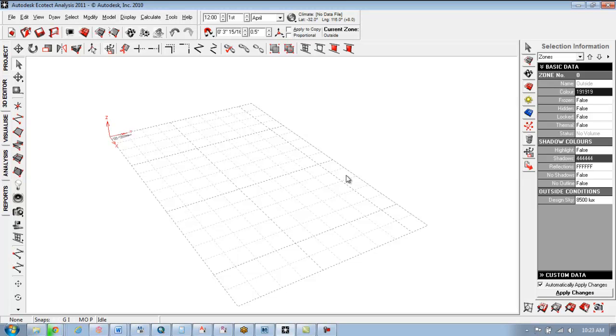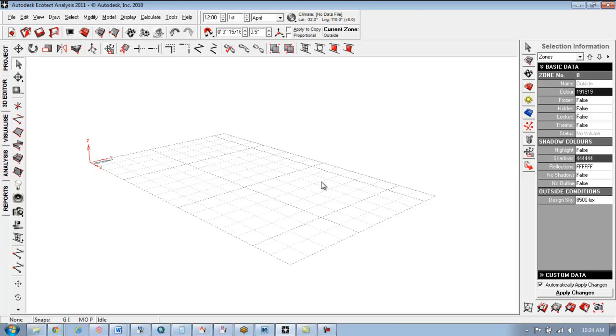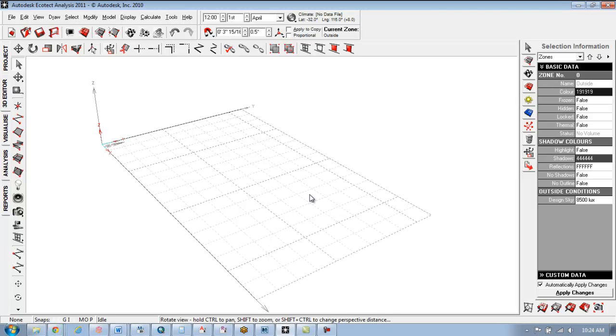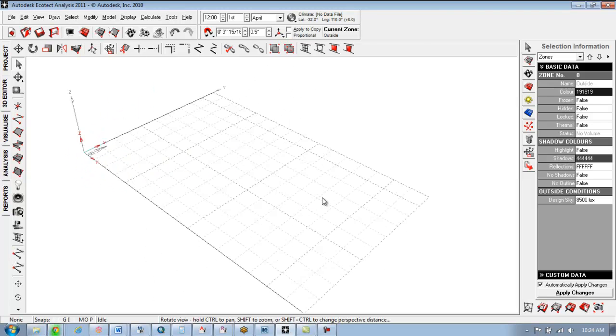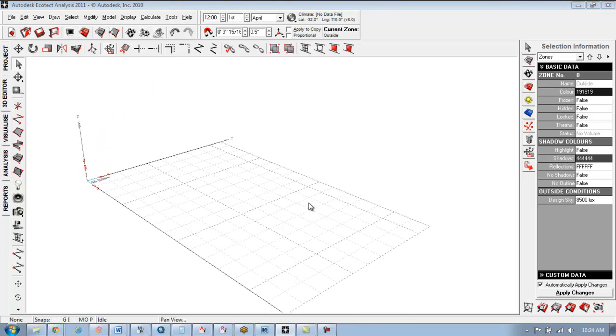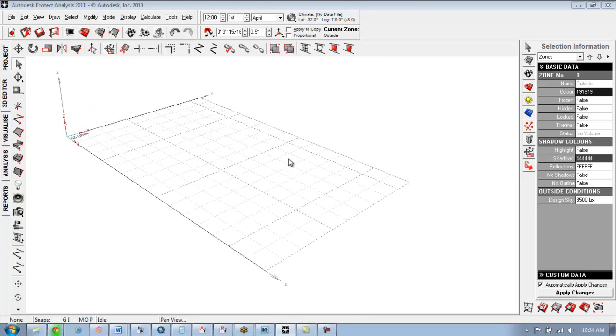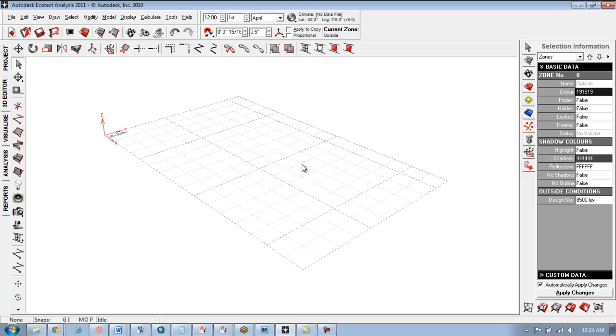This was developed by a professor down in Australia. So by default, a lot of things are going to be in millimeters and Celsius and all that, so you can tweak it. Basic navigation is actually the reverse of SketchUp. So if you're going back and forth, you're going to be kind of confused. But the right button allows you to orbit, and the scroll wheel, when pressed down, allows you to pan. And then, of course, you can zoom in and out with it.